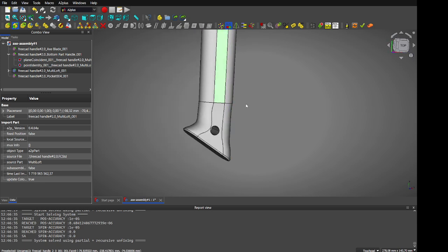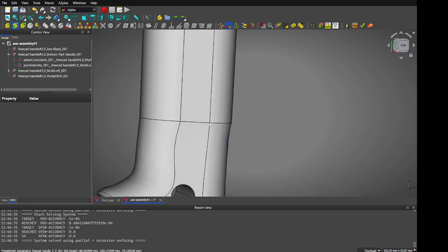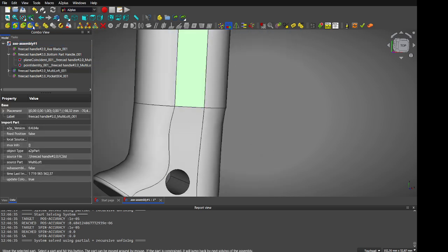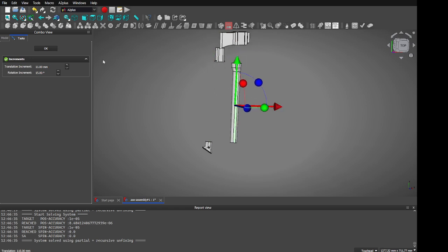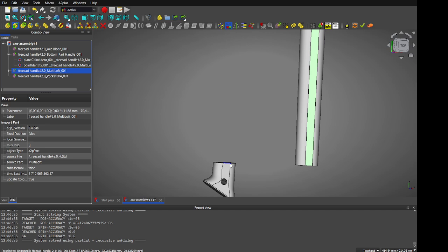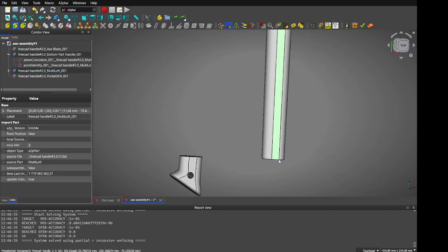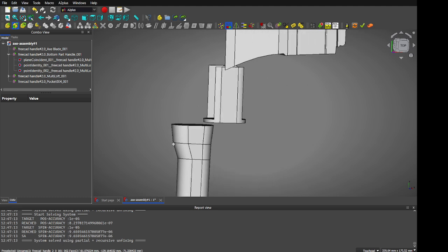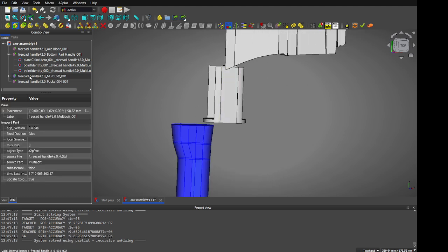And it's nice, but I know also that one more point of constraint is here. So again, move this part outside of the desired point, select the point, and select this point. When you select it with holding the control key, keep in mind to unselect unnecessary surfaces, and you have 2 points to which you can apply a constraint, and here is the constraint, so accept. Next we are switching to another part, and one more time we will have the same operation, but here